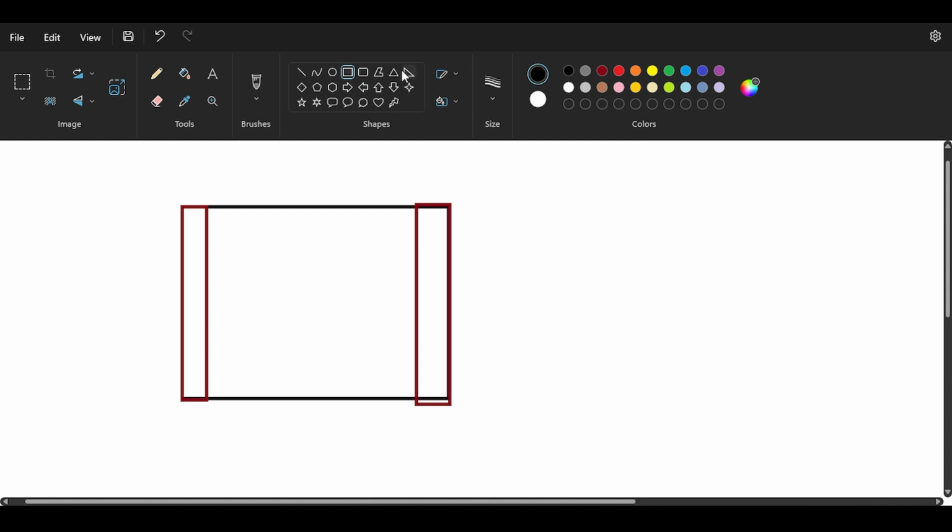And typical bricks, depending on your country, and this is very important now, typical bricks in the region I'm working at is like 400 millimeters in length and 200 millimeters in height, and the thickness is different. Let's focus on the height. Now, to be able to work cleanly here, when I make my beam, first of all, I told you I'm gonna make a simplified version of the beam, so it's gonna be in the middle. That's not my point, but at least when I want to select the height of the beam, I select the height of the beam to be multiples of 20, so that I don't have to put half bricks in the wall. That's point number 1.